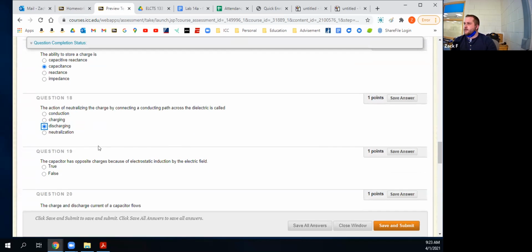By the way, if you're ever in a scenario where you have big capacitors in something like an old light fixture or a variable frequency drive, like you'll see upstairs in the drives classes, those things hold charge. It's like a battery, right? If you don't discharge them and you touch them, you're going to get walloped by whatever voltage is being put on them. So to discharge them, you take a screwdriver or something across the two terminals.